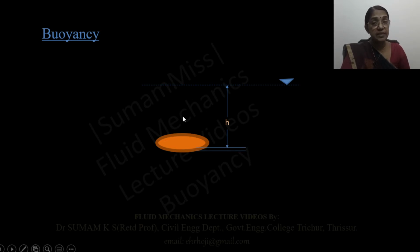We have learned previously that pressure at any point in a static mass of fluid depends upon its position with respect to the free surface and the specific weight of the liquid. So the pressure force that is acting in the downward direction on the top surface of the plate is equal to ρf g h into A. So ρf g h is the intensity of the pressure and A is the area of the plate.